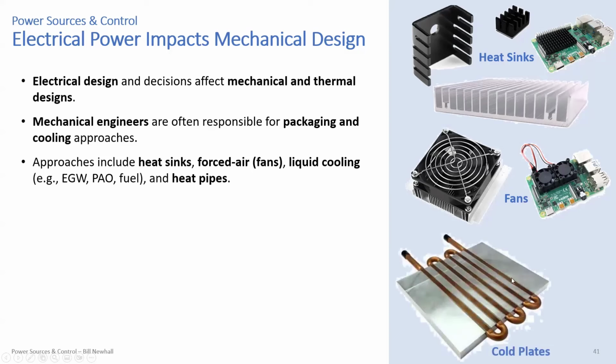Let's see what else. And cold plates. Okay, so cold plates can have liquid flowing through them to try to maintain a constant temperature or limit the rise of temperature of that plate. And heat pipes have different materials inside to try to get the heat transferred from one place to another more efficiently than just a metal rod. So you can look at those. There's different technologies there. But these all fall in the domain of mechanical engineers, typically, to get the heat out.